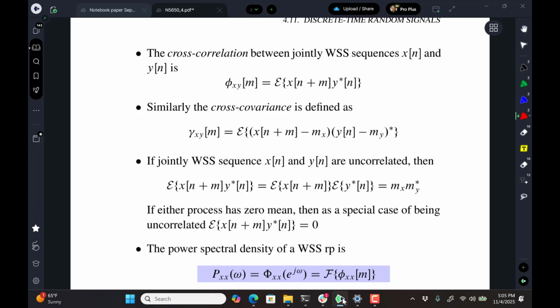Okay, at any rate, so cross-correlation has a real practical value. So here it's X and Y. In most of what we're going to do in this class, it's just going to be the input and the output of a system, but it could be, like I was discussing, jamming and noise for sure. So X times Y conjugate, that's the cross-correlation, and then if we subtract the means away from each of the signals, which is what is going on in here, there's X minus its mean and there's Y minus its mean, then that becomes the auto-covariance.